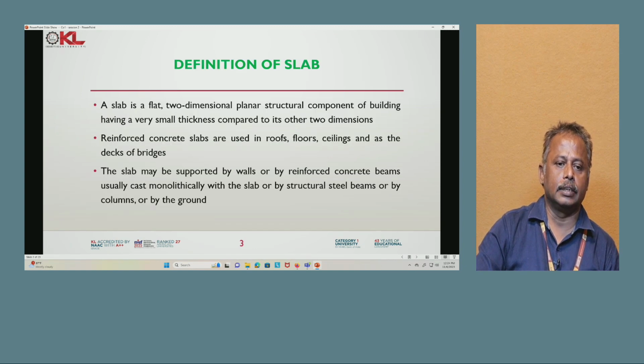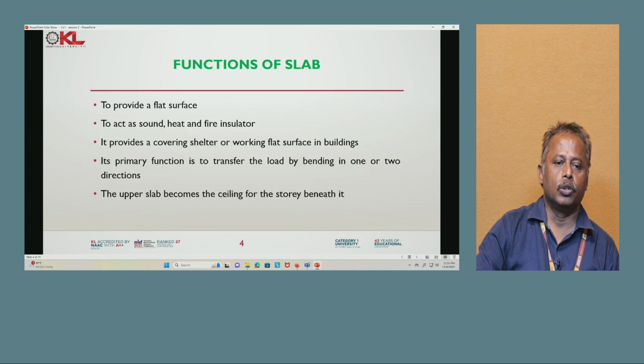The slab is a flat, two-dimensional planar structural component of the building, having a very small thickness compared to the other two dimensions. Reinforced concrete slabs are used in roofs, floors, ceilings and as the decks of bridges. The slab may be supported by walls or by reinforced concrete beams, usually cast monolithically with the slab, or by structural steel beams, or by columns, or by the ground.